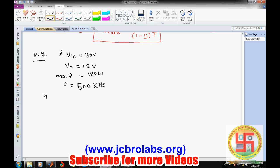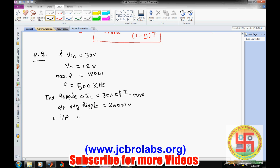And for the inductor ripple, that means del IL, we want it to be 30% of IL max, the maximum value of inductor current. And the output voltage ripple we want within the range of 200 millivolt. Okay, now from here we can find the different values.